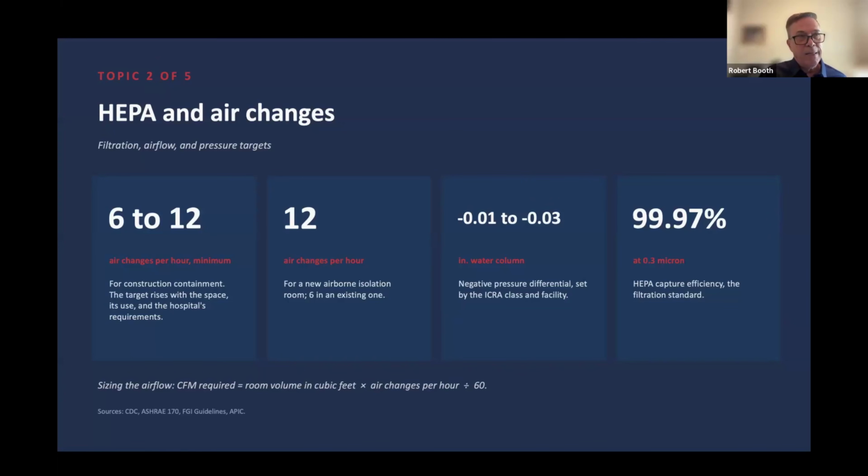Now, basically, we know that a HEPA filter will encapsulate a lot of harmful particulate, but not viruses and not bacteria all the time. So the best way is to take that to an area where there's no patients, and wear some kind of respiratory protection if you think there's contaminants such as molds and other items.